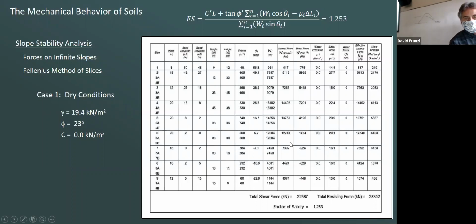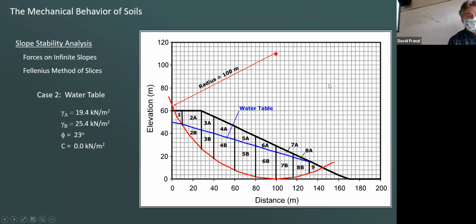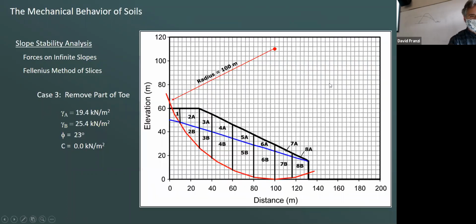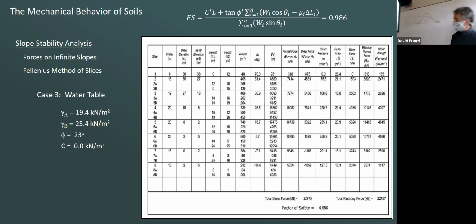So in this case, we have to subtract off all of this. We actually use a negative theta as well, because it's directed back into the slope. When we remove slice 9, we basically take slice 9 out. I don't even have to change my table from the previous one. I just zero all that stuff out and sum them all back up again. And what happened? We lost that variable force that's holding the slope in place.